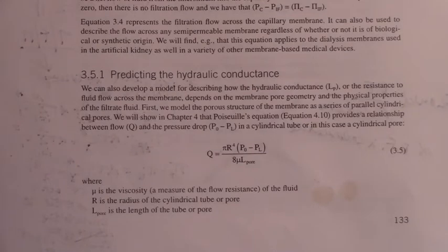But in the early part of the design process, you don't have a lot of data, you don't have all the information. And as engineers, we have to make some assumptions and make some predictions about how we think the system's going to behave. Now, you can easily measure the hydraulic conductance of a membrane in the laboratory. If you just take pure water and apply a pressure across a membrane, and you measured that pressure drop across the membrane, you measured the flow rate, and you knew the surface area of the membrane, you would be calculating the hydraulic conductance of the membrane.